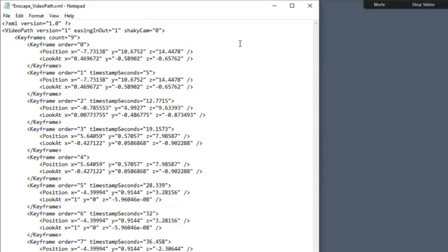All right. From the end of that second camera to the next camera, we want 5 seconds to transition and then another 5 seconds. So we're going to take this value and make it 10. Then we're going to get to the next one and make it 15. And then where that camera is right on top of that other camera, and it doesn't look like I've got a frame order here, I'm just going to grab this value and Control-C to copy it and Control-V to paste. So from the first resting for 5 seconds, to the camera that's in the middle, to the last camera 5 seconds, and then resting for 5 more seconds. So that's going to get us at 20.